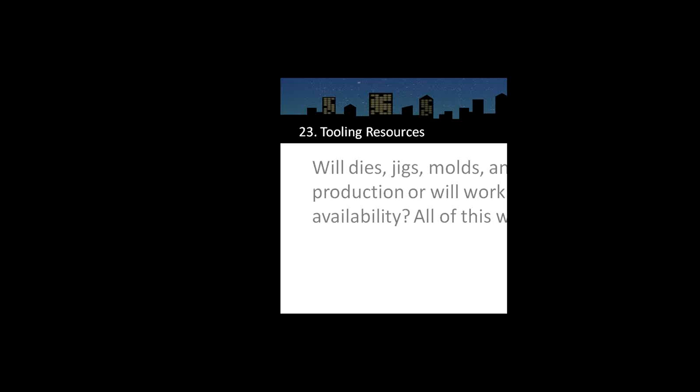What's going to happen from an MRP perspective, if it's not looking at my tooling requirements, is it's going to say that I can schedule both of those work orders at the same time, even though I only have one die available. It's the same constraint issue I would have if I have only one machine. But unless the MRP system or the scheduling system has visibility into that constraint, you're going to have issues when those orders are actually suggested for creation.